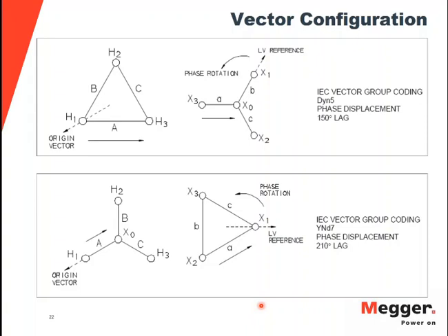When we talk about the Megger transformer ohm meter, the test set specifically designed for winding resistance, the difference that it has in addition to your regular 10 amp or 50 amp current is that it has a discharge circuit inside the unit that is capable of dissipating the energy stored in the inductor or in the coil.